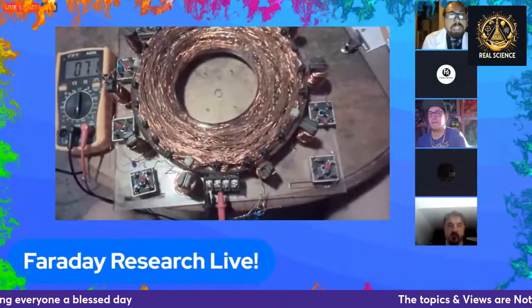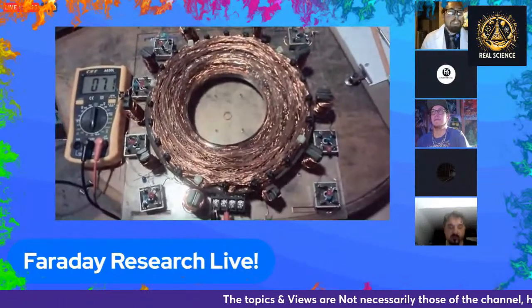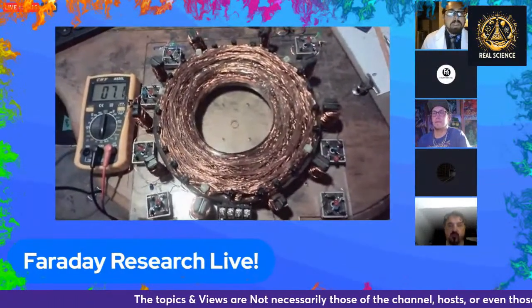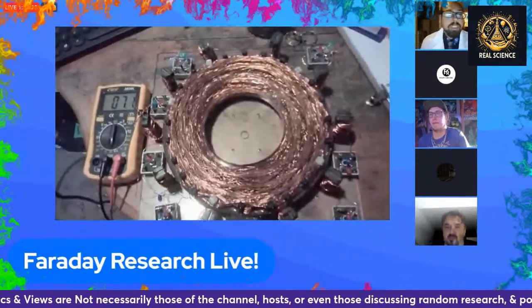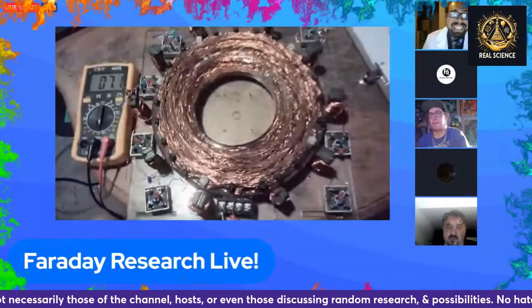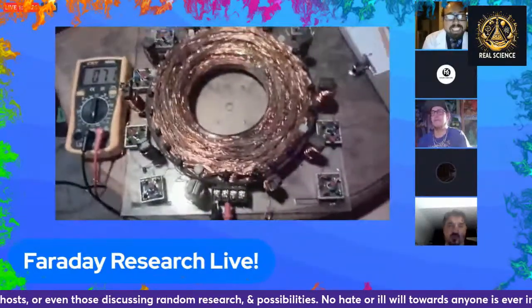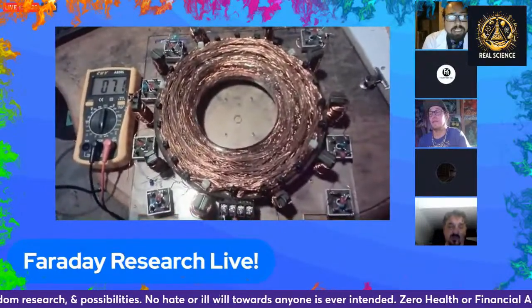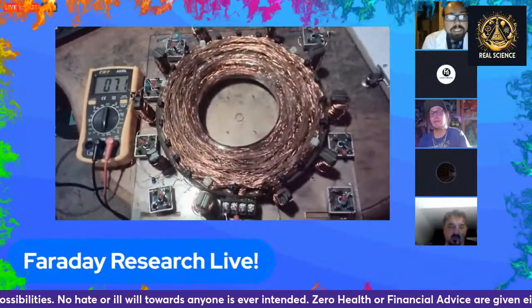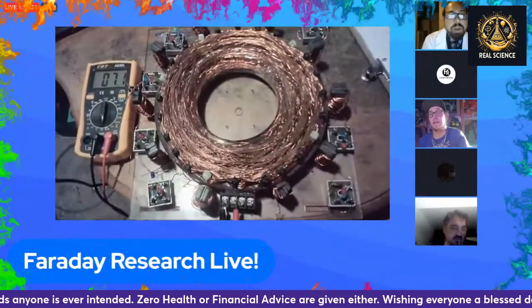See, even that, disregarding the current, even transforming the voltage like that with a 1-to-1 ratio coil is supposed to be impossible, right? Supposed to be, but this is based on geometrical form. Well, no, it's a 1-to-1 ratio of turns, but not the same gauge, and that means the resistance is different, and the flow rate of current through the two of them is also different. Oh, so there's two different gauge wires. You got to keep that in mind.